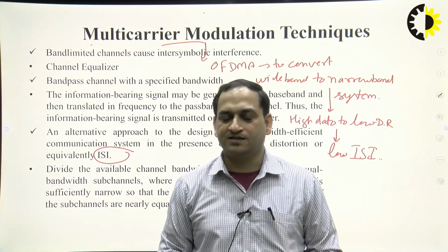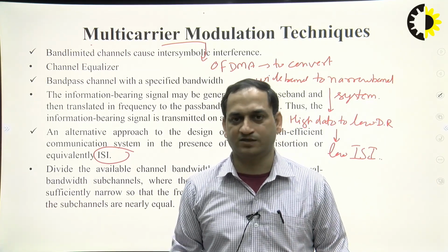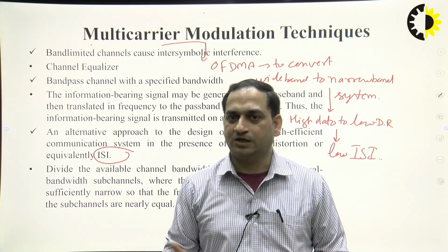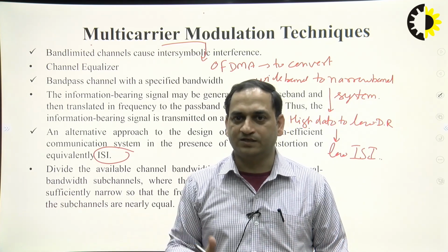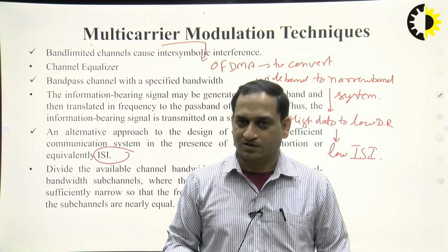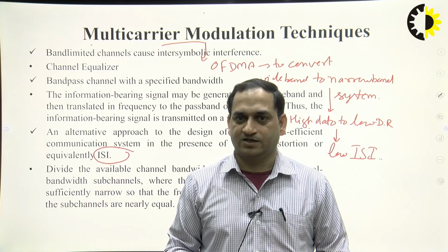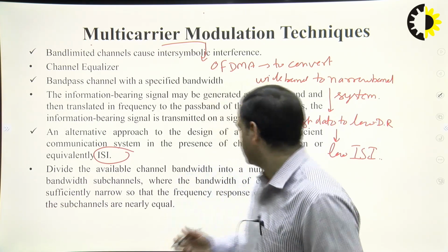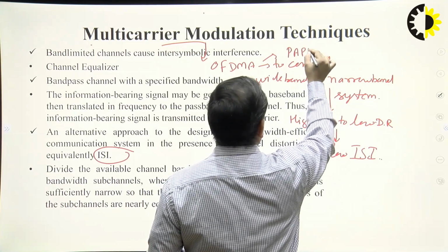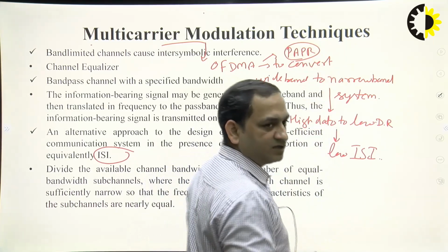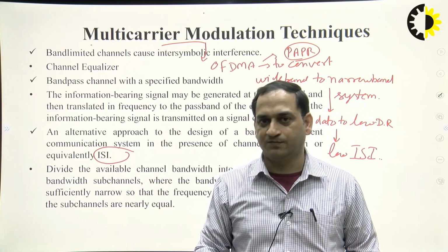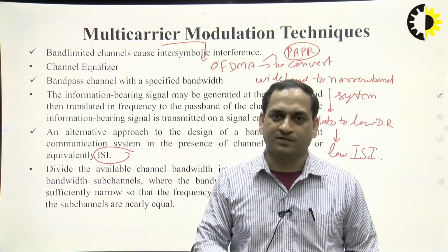All the 3G and 4G techniques use multi-carrier modulation, in which the OFDM system is used for the uplink or the downlink. For the downlink we have the OFDM system, and for the uplink we have the SC-FDMA system. The reason is power control, since the OFDMA system suffers from PAPR, the peak to average power ratio. To minimize all these things, we have to take care about the SC-FDMA or OFDMA system. Okay, thank you very much.